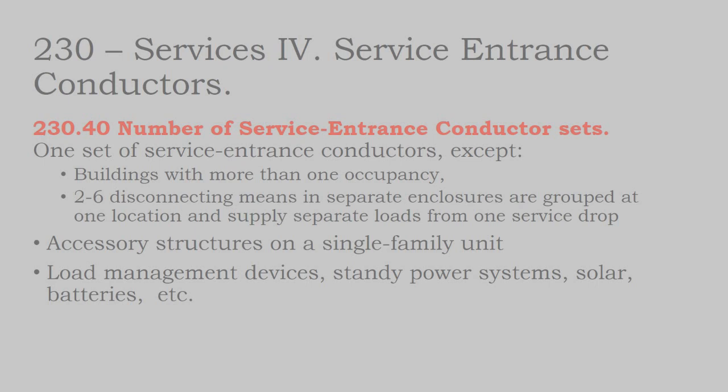As long as they are grouped together. If you have a special need to have more than one set of service entrance conductors, such as buildings with more than one occupancy, you can have 2 to 6 disconnecting means grouped together in one location from one service drop.